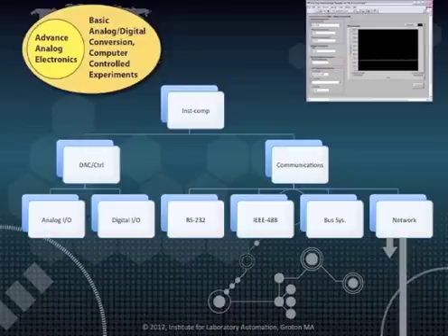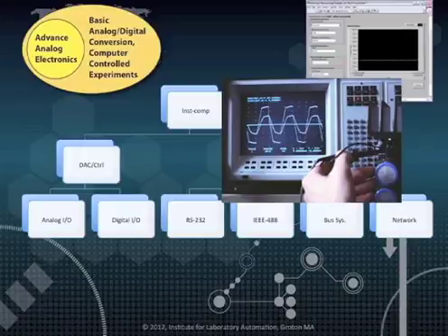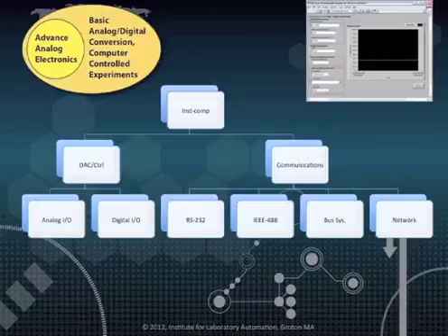We discussed data acquisition and control when we were looking at the connection of the real world to computers. The real world consists of signals in the form of voltages, physical movements such as rotation of a shaft that have to be converted into voltages, or the opening and closing of switches. If we want to read voltages, or control things through the generation of voltages, we use analog input and output. Reading a voltage is done through an analog to digital converter, a device that measures the voltage and represents that voltage by a digital value. If we want to generate a voltage to control a device, we use a digital to analog converter.